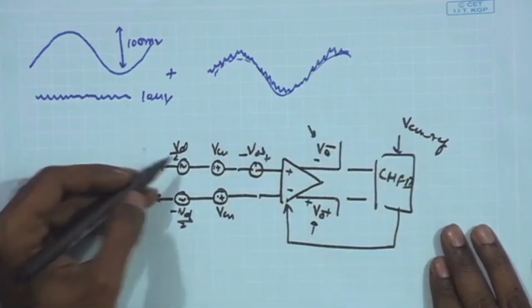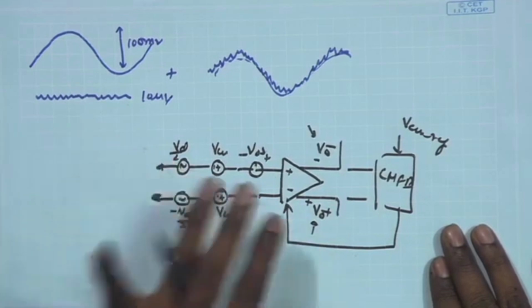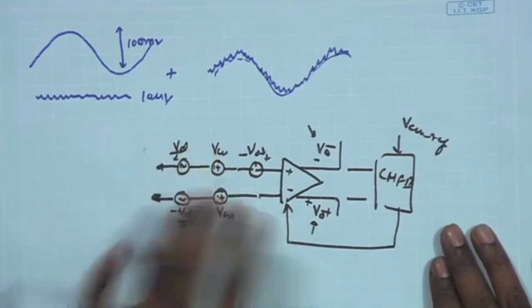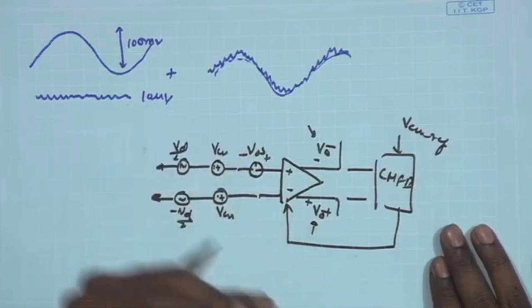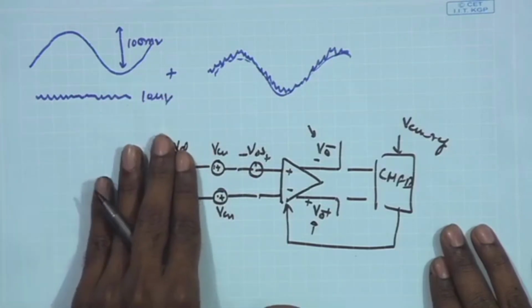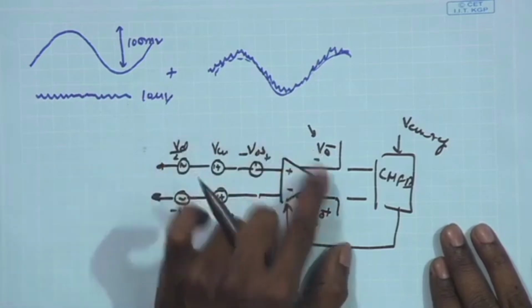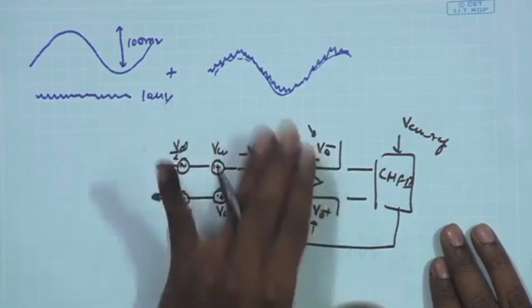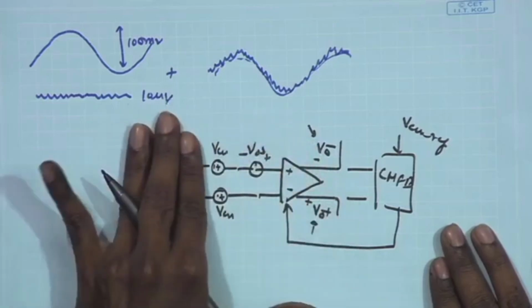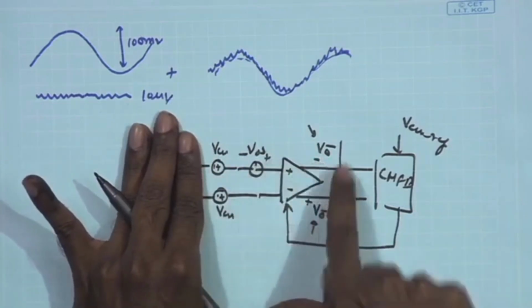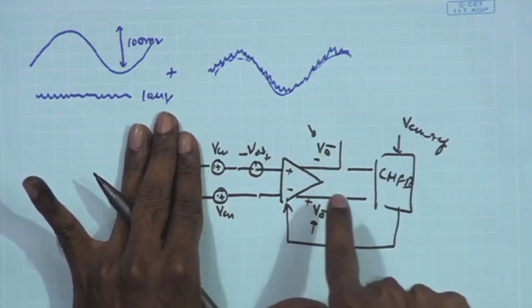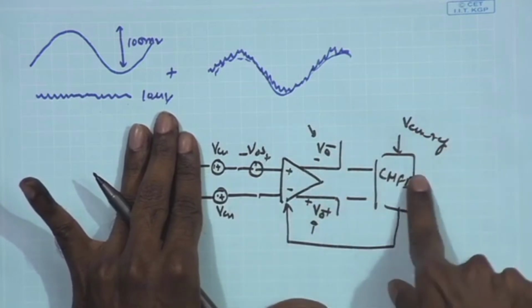Suppose I try to see first of all what is happening when the input is set to 0, that is how we calculate or observe the effect of offset. So we set the input signal to 0, apply the same DC level at both the inputs, and then try to see what is the output. Ideally, if the transistors are fully matched, if you are applying the same DC level VCM to both the inputs, the output DC level will also be exactly the same, equal to the common mode level.